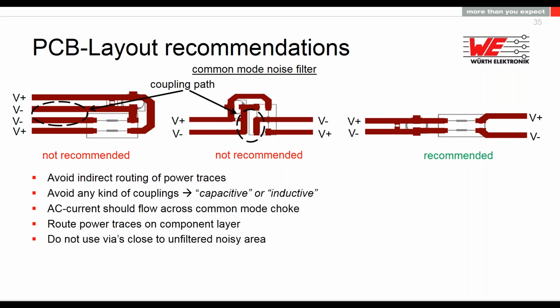I told him, don't change too much on the board. Try to avoid any change in a different place because maybe it will generate something different, and you scratch on one side and itch on the other side. So he made redesign number 1. Noisy area is going in, noisy area is going out, and actually it should be filtered, but it's again noisy. He said he did not pass the EMC test.